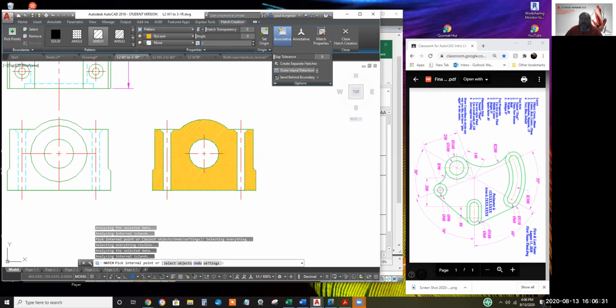Down here, if you've got a bunch of concentric circles, circle, circle, circle, do you want every other circle to be cross-hatched so there's a white space between all the rings of cross-hatching? I imagine that comes up pretty rarely, but you can select different options for how it handles these islands in the middle. I'm not even sure if there's an option to say disregard. Anyway, we selected the area.